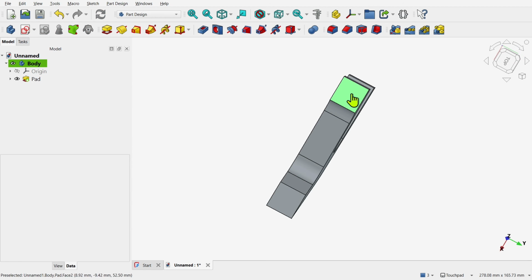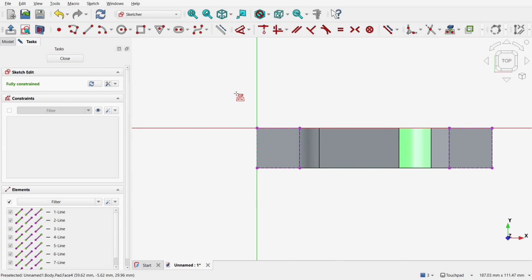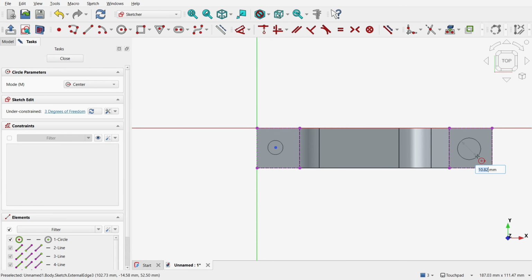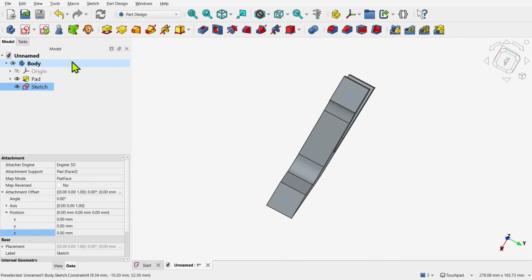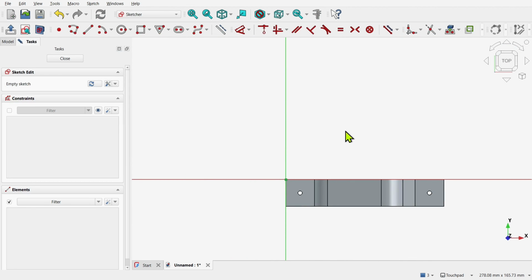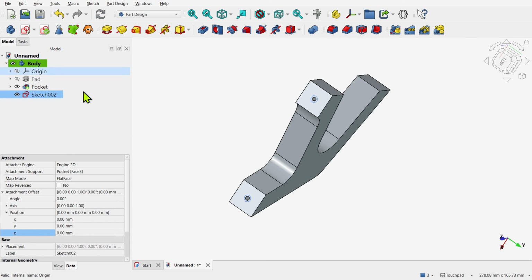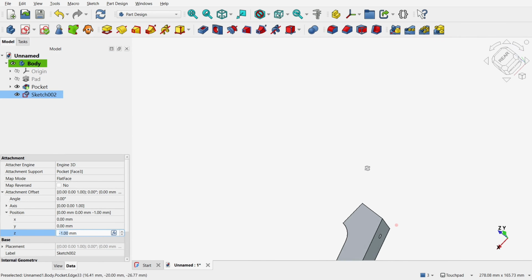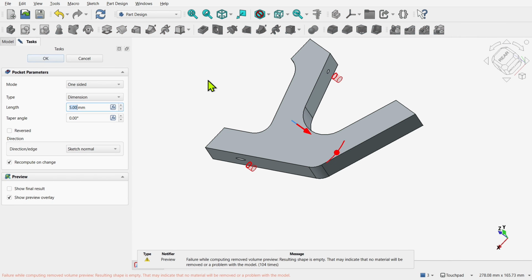The key takeaway is that intent matters. Feature chaining is fragile when intent is unclear, attachment is to fragile features, or is applied when large design changes are expected. But when the intent is simple, local and linear, chaining is perfectly reasonable and often is the more efficient workflow.